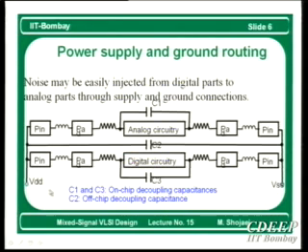We don't have any absolute potential. VSS is just a reference. As long as my VDD is constant with respect to VSS, that's enough. That's why it is called decoupling. It decouples noise which is injected from any modules on VDD and VSS.